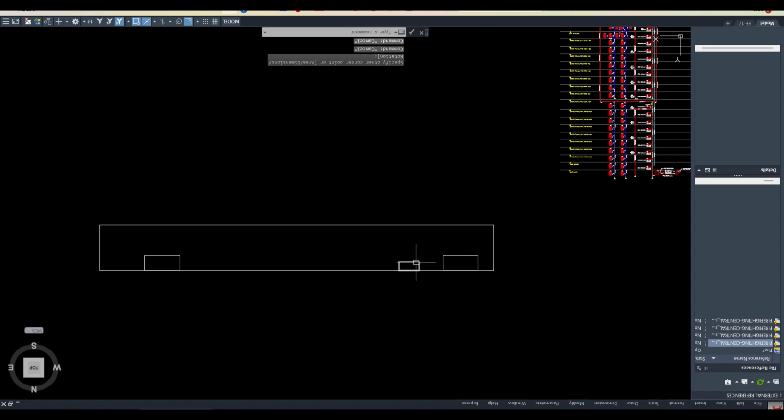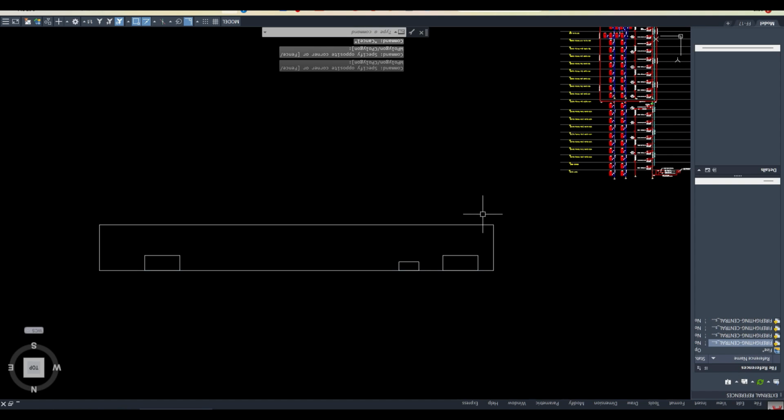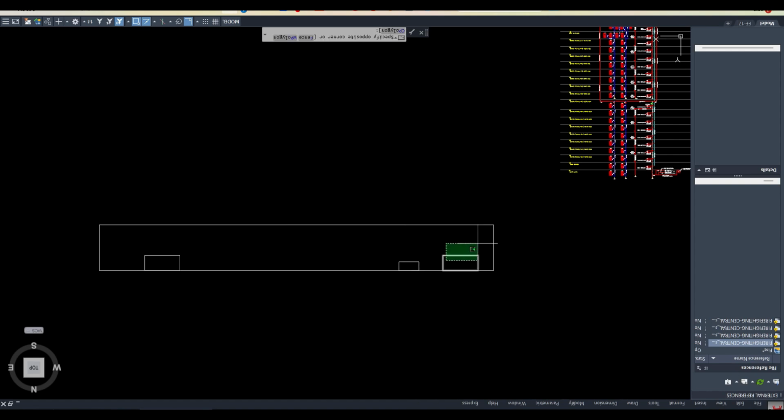Okay, 45 meter. So in that case, if I install a hose reel here, right, let's say it's 5 meter away, which is acceptable. It should not be more than 6 meter, right? So can it cover till the dead end of the corridor? Can it? No, sir, because the length of the hose reel is too short. The complete corridor is 45 meter, and this is only 5 meter away from the staircase. Okay, and let's say this staircase is covering 5 meters, so 10 meter maximum, right? So these both are within the 10 meter, right?